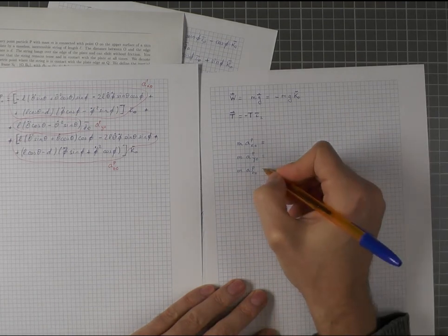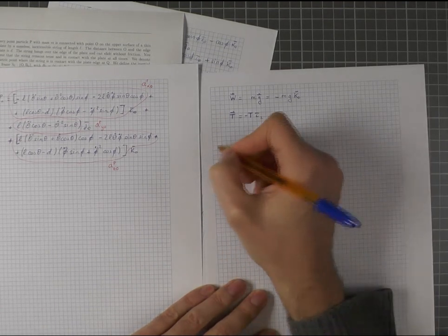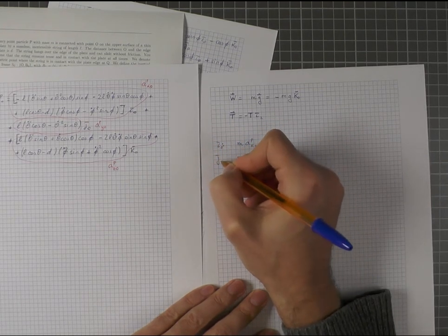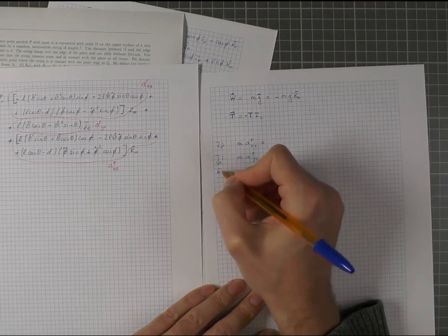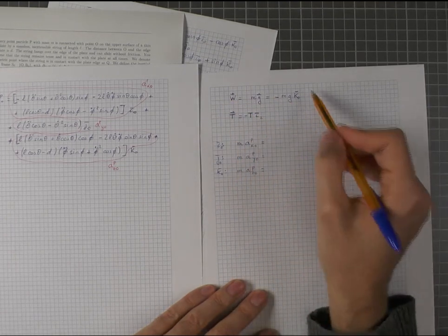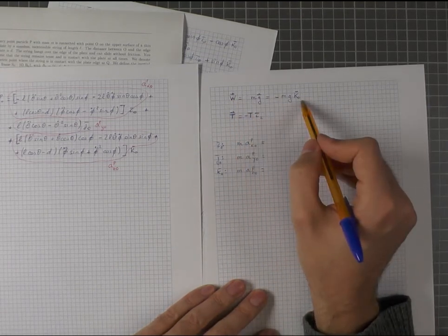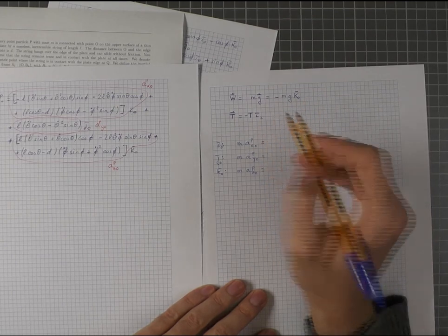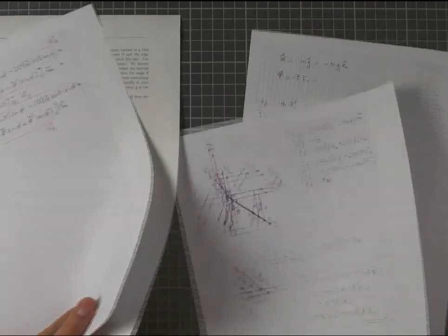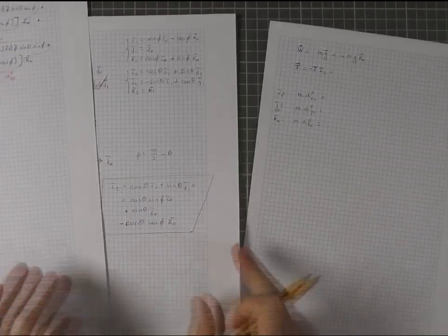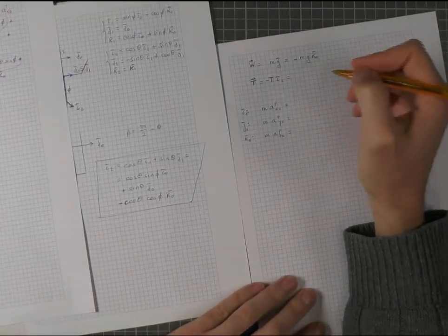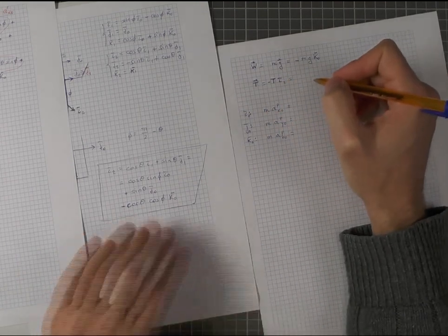So in order to have the forces in this basis, okay, this is in the direction of I0, okay, this is in the direction of J0, and this is in the direction of K0. So in order to have the forces in this direction, we need to project the forces in this basis. So we see that the weight is already in the K0 direction, so that's fine. But the tension is in the I2 direction. So we need to go back to our definition of I2, okay, which we have over here, all right, and rewrite the tension in terms of that expression.